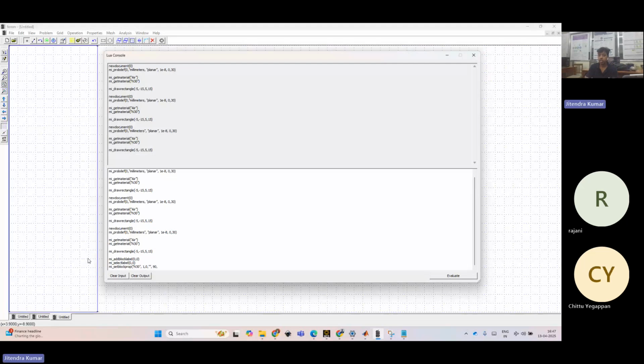90 is the magnetization orientation, then again 0. So what does this line mean that I'm going to explain? The first thing is clear, that is magnet grade. Now, second, 1, 0 could be replaced with 0 and something else. One is auto mesh, then manual mesh you have to keep as 0, the size of the mesh. If you replace one with 0, that will assign a manual mesh. And now, for the mesh size, here you will have to define. So this 1, 0 is changed according to your requirement.